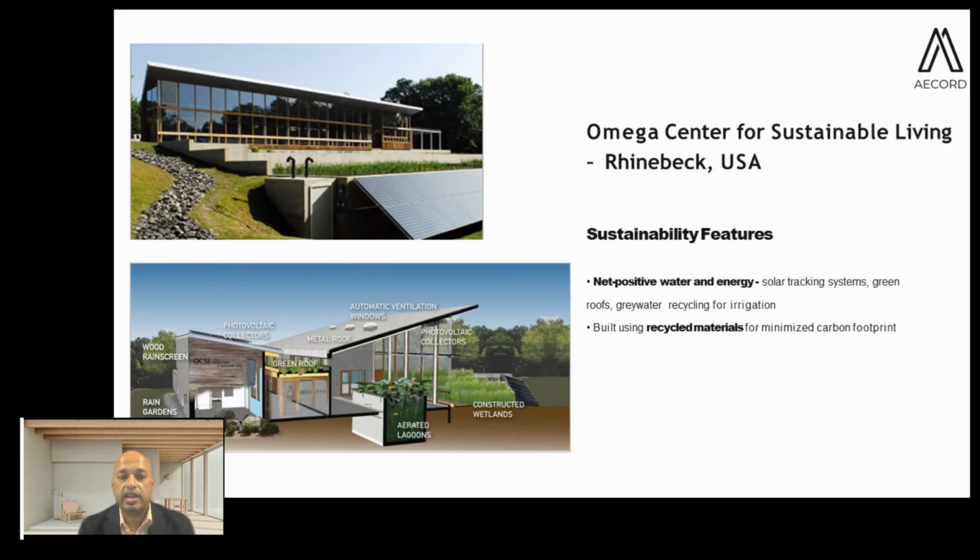So when we do an LCA analysis and carbon footprint analysis, we take into account the energy saving in the installation stage, and the energy saving in the operational stage. What is the reduced embodied energy of the material, how much of recycled content and how much of recyclability is there, and what happens to the material after the life cycle. So it's a holistic approach of complete life cycle analysis, from extraction of the material till the end of the life cycle of the building, and that material goes back to recycling or landfill, whatever it is.